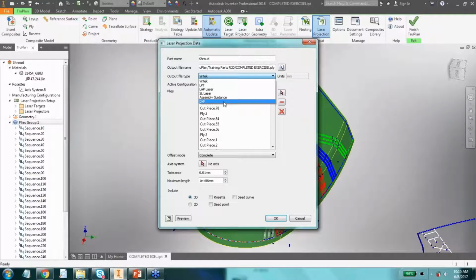So you could read this back into TruPlan. You could use those shapes in the DXF file to kind of rebuild surfaces, whatever you like with that. You could even read that DXF back into CATIA to compare against your original surface and your original design. So this DXF is a new format, and it's more geared towards generic file format production than any of these specific brands.